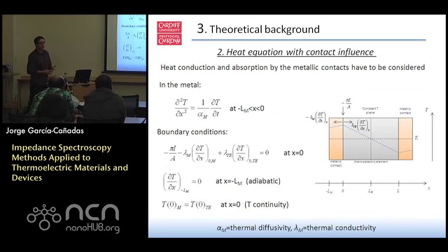Let's look now at a second approach. Now we are going to take into account the effect of the contacts. So now we have a metal strip. If we look just at the left part of the element, we now have a Peltier heat flux which can go in two directions. It can be absorbed and transported along the copper, our contact, and also towards our thermoelectric element.